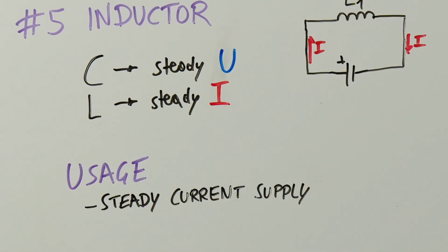They are essential for maintaining steady current supplies, leveraging their energy storing capability in applications such as switch mode power supplies. Moreover, they are often combined with capacitors to form LC circuits, effectively reducing ripple in switch mode power supplies, where ripple is a periodic variation in direct voltage, typically stemming from deriving DC voltage from alternating current.